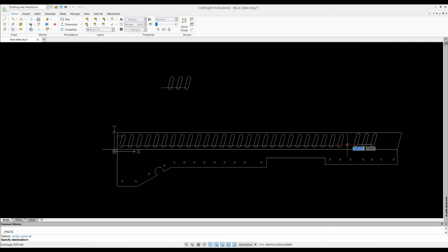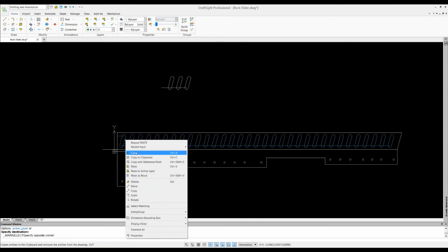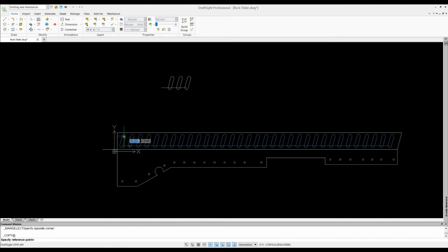If we were smart, we would have deleted all those building lines so we don't have to go through and delete them again. So that looks pretty good, but we ended up with kind of an odd spacing at the end. So I don't know if I like that. So let's try to center this up a little better. So let's just cut this whole thing out, not hitting any other lines. Let's go cut. Ooh, but we can't cut with a reference point. Okay, let's copy with a reference point, and I think let's just do here, and then let's go ahead and cut it and move it.